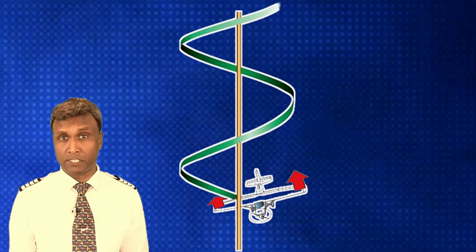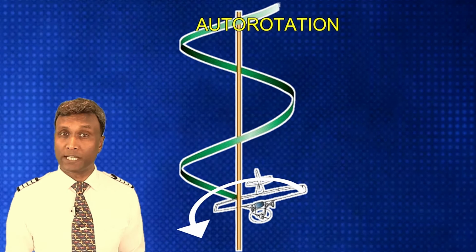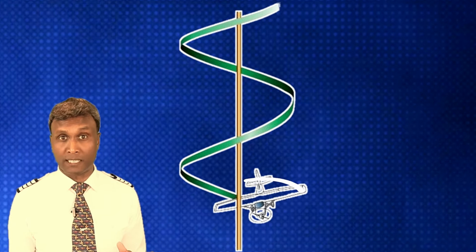Essentially, one wing becomes more stalled than the other, leading to a difference in lift generation. The wing with slightly more lift creates a rotational force towards the other side, initiating the spinning motion as the aircraft descends. This auto-rotation phenomenon is a critical aspect of understanding and recovering from spins in flight training and aviation safety practices. Spins are not something you want to experience unintentionally.